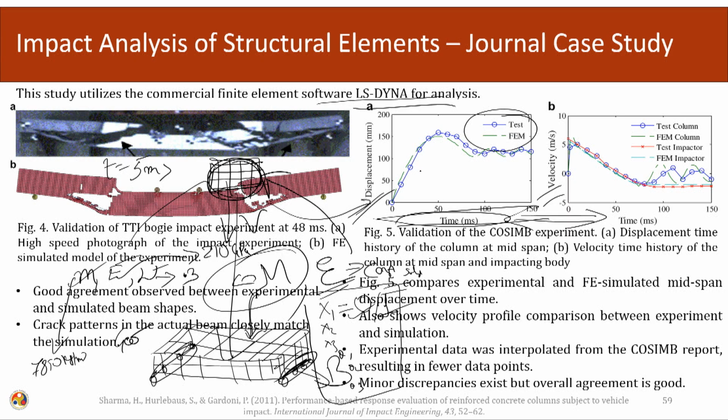So, first we validate with any existing experiment and then we do our own simulation. We can get the displacement quantities, the velocity quantities, stress quantities or any other quantities that we need. Using commercial software, we normally use LS-DYNA and we can get the simulation.